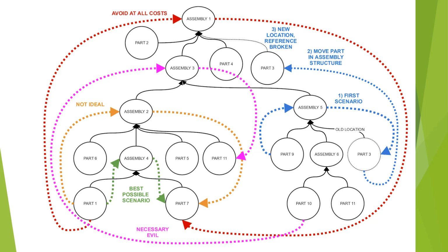So not ideal, right? Is to go 1 level higher. This is a subassembly, so I could open up that subassembly. But what I often see when I'm at customers or doing consulting work, somebody has a big assembly open and they just, whatever assembly, whatever level, they click edit part, they start dropping in external references. And you're making this loop, which is not ideal, right? The top one there, avoid at all costs.